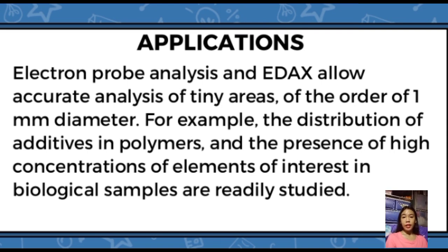It is advantageous in analyzing mineral and cement composition and examining petrochemical products. Electron probe analysis, coupled with energy dispersive analysis of X-rays, or EDAX, facilitates precise analysis of small areas, typically about 1 mm in diameter. This capability is especially useful for studying the distribution of additives in polymers and detecting high concentrations of elements of interest in biological samples.